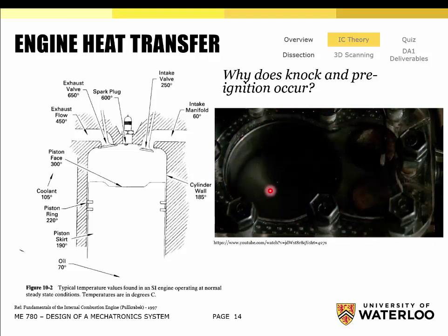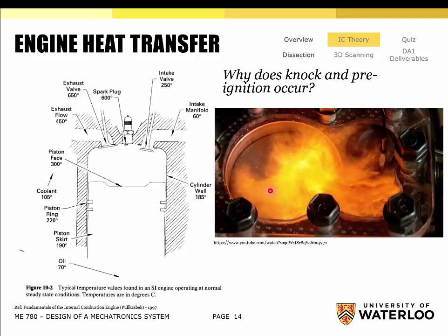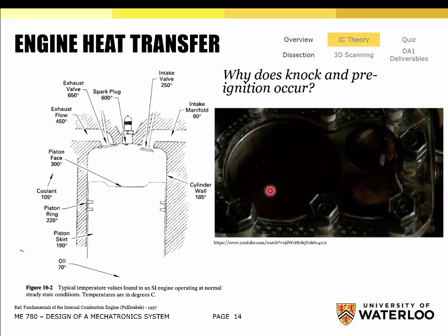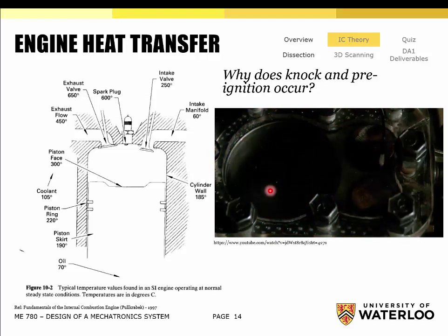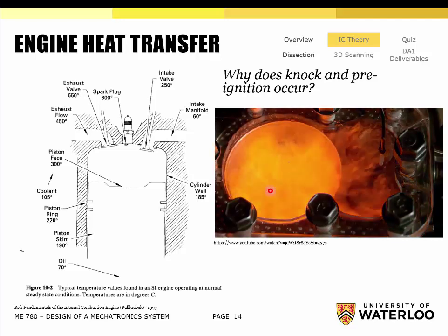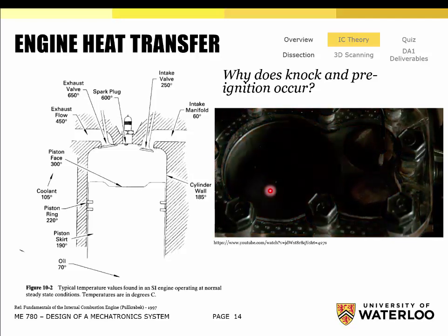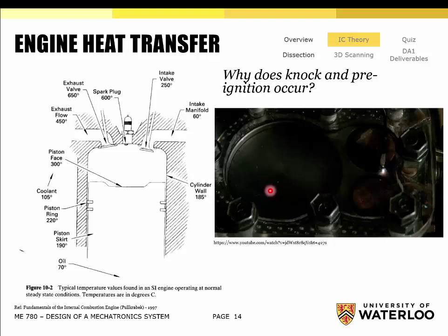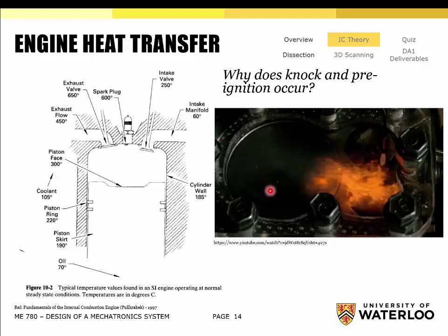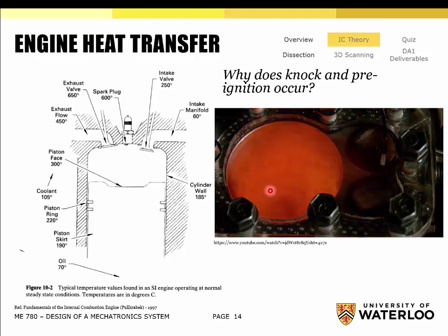Before. Okay, that's because of the fact that it takes time for the actual mixture to ignite and start to burn. If we want to push on the piston in the downward part of it, we don't want to start the combustion process in the downward part of it. We want it to already be burning in the downward part of it. So we need to provide that small amount of what's called ignition advance. So that's useful. The other thing is when it actually ignites, you might notice that there's a small amount of delay. It doesn't instantly start flaming, okay? You'll see that in the next cycle again.